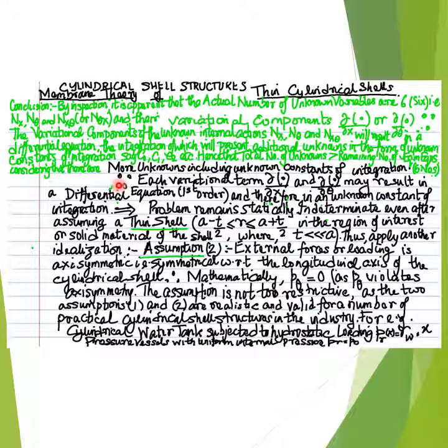Hence, the problem of the solution, that is the membrane solution of the unknown internal in-plane or membrane actions nx n theta and nx theta with reference to the differential thin cylindrical shell element presented in the figure in one of the earlier slides remains indeterminate